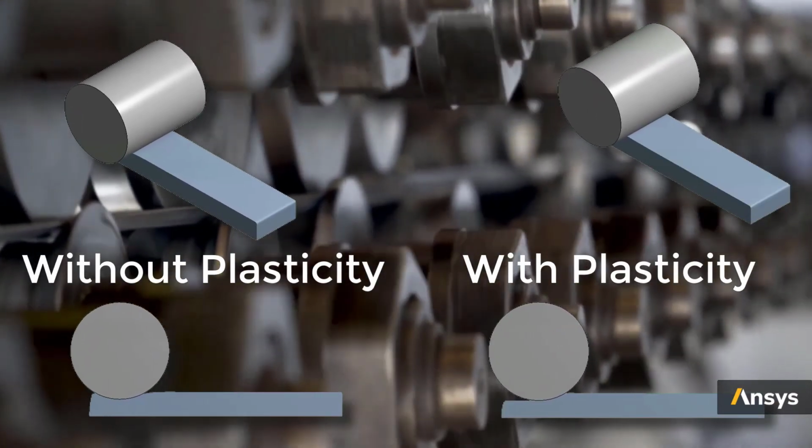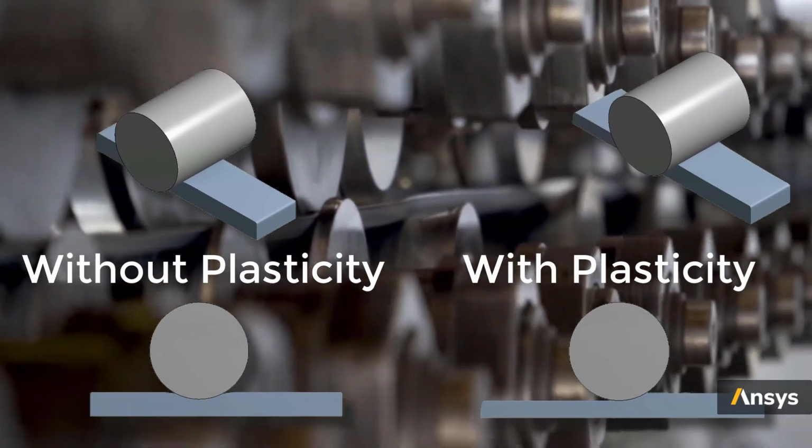However, a material nonlinearity in general is associated with a physical behavior, and ignoring it in the analysis may result in incorrect predictions. For instance, as mentioned earlier, most metals can be approximated to have a linear behavior at small deformations. However, if we extend this approximation to larger strains as well, then in an application such as cold forging, we will ignore the effects of metal plasticity, which introduces nonlinearity in the material behavior, and end up with incorrect results. This is because the key physics that's resulting in permanent deformation during cold forging is the metal plasticity. And assuming a linear material behavior will disregard metal plasticity, and hence our metal samples don't undergo any permanent changes in their shape, which is incorrect.